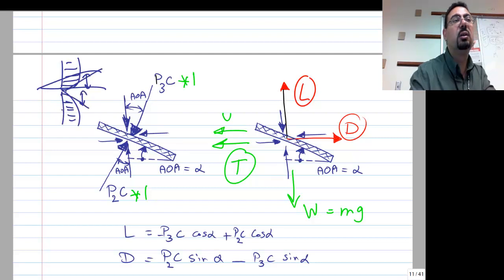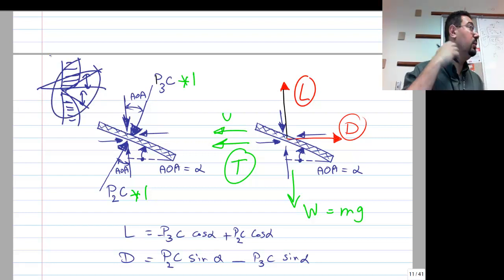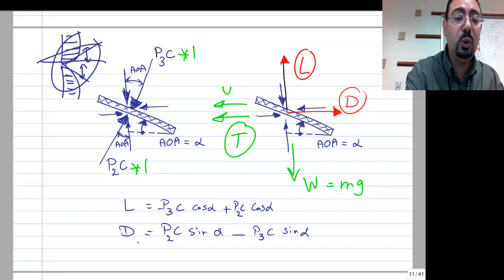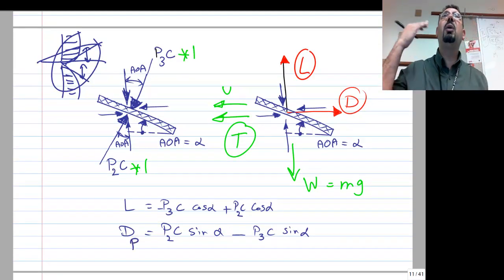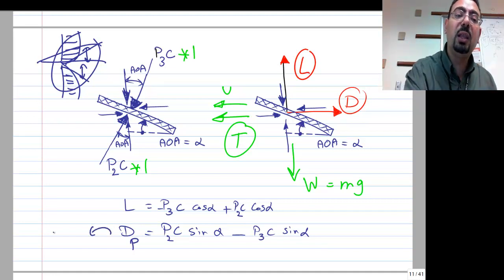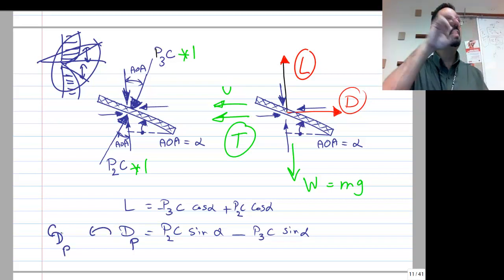That's where the shear and the viscous drag is happening. This is not in this course. This is when you take experimental fluids in the spring, 4273, you'll be able to calculate this. So really, that drag, if you want to do a good job, you would call it DP. You are trying to remind yourself that's only the pressure drag. On top of that, there is a skin friction drag that we are not calculating. All right? And the drag coefficient that we will calculate in a second, which is going to be CD, we will call it CDP. It's the drag coefficient only due to the pressure.